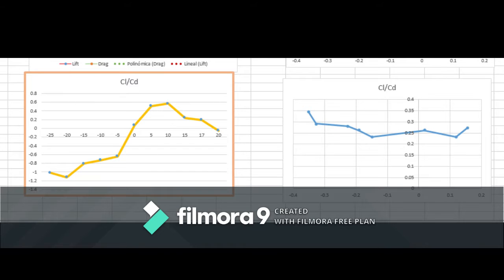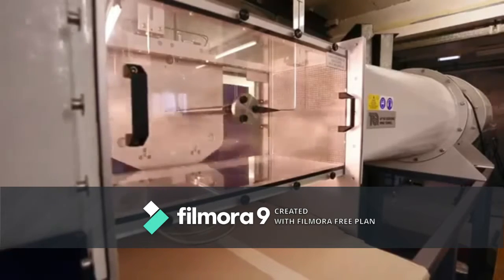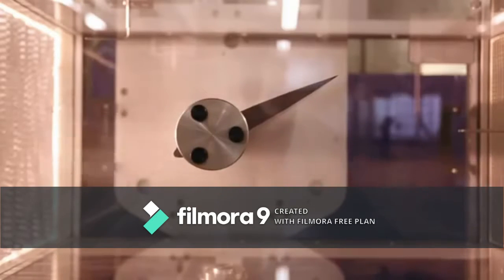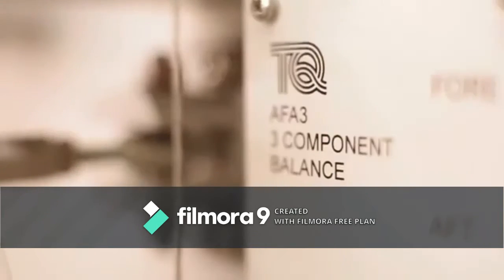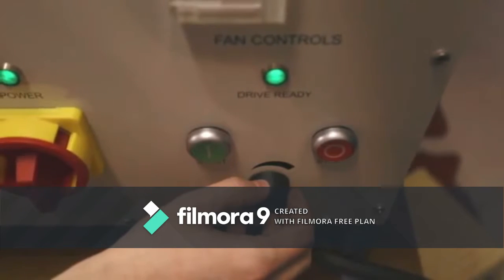This means that when our profile is at an angle of attack equal to 0, the contact area of the airstream is minimal. Therefore, it is the point where the drag is almost 0. When there is an angle of attack of 20 or 25, there is a greater contact area. This means that the drag will be greater. In a few words, if there is a greater contact area, it causes a greater resistance to the air.